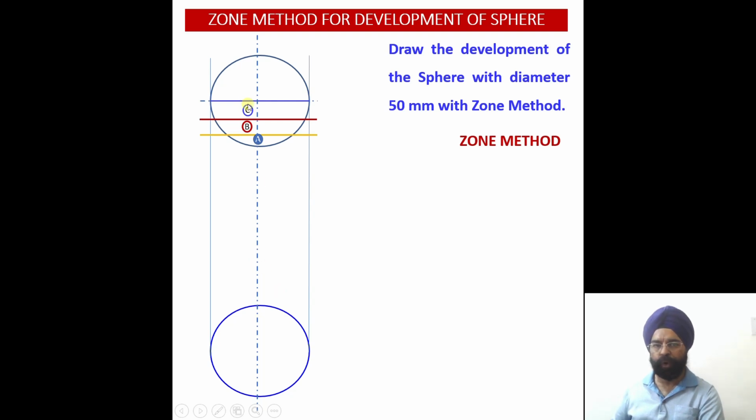So if I draw both of these, the front view and the top view, close to each other, it might happen that the projections of the slant edge enter into my top view over there. So I wanted to show a distinct front view and a distinct top view. That is why I have kept a reasonably good amount of distance between the front view and the top view.